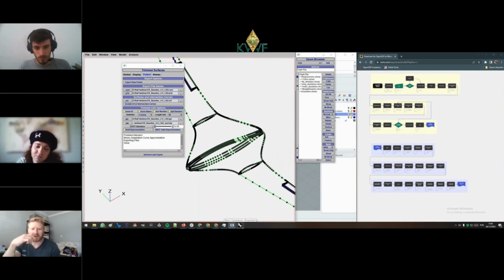So part of me is wondering, did you try and use different units, like convert the OpenVSP model to millimeters and then go straight to Rhino from that format? Did you adjust any of the step tolerance to match up with the Rhino accuracy, to try and get the decimal precision of what comes out of OpenVSP into Rhino to be more aligned, to see if it would be happier with those surfaces?